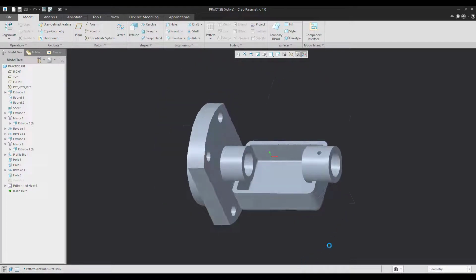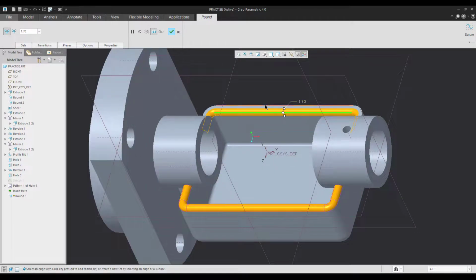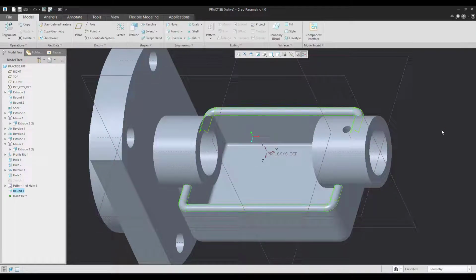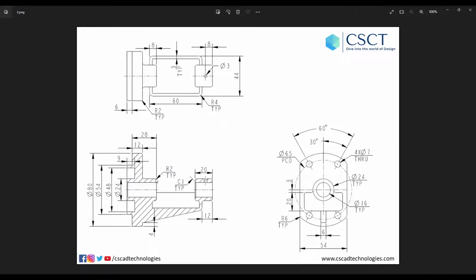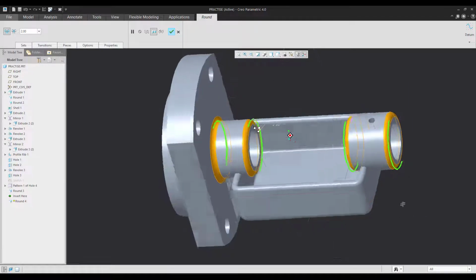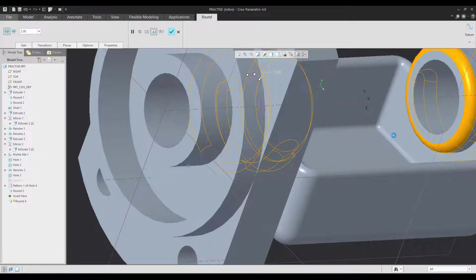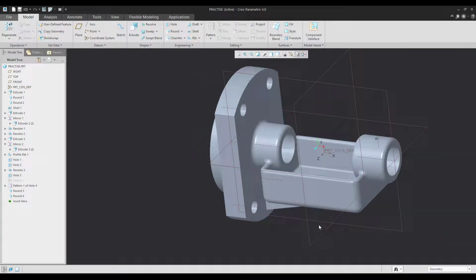Now, let's get into the finishing operation, which are rounds. There is a full round on this feature, which is a dome type of structure. So let me do that first before proceeding. Now, the rounds which are given here and on the bodies are actually 2. So let me take that over here, over here, over here as well. This is 2 mm. I can give it on this corner as well. It's actually given to that corner as well. This is the 2 mm.